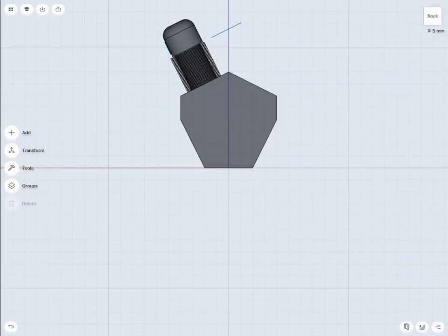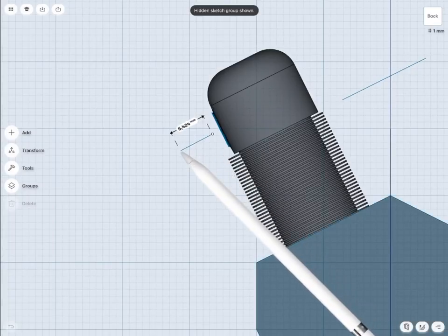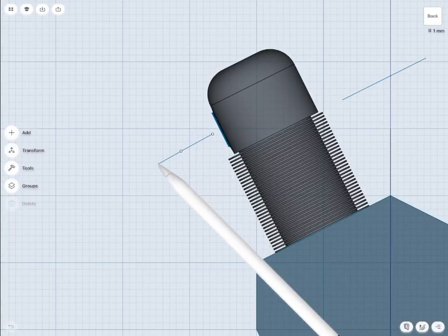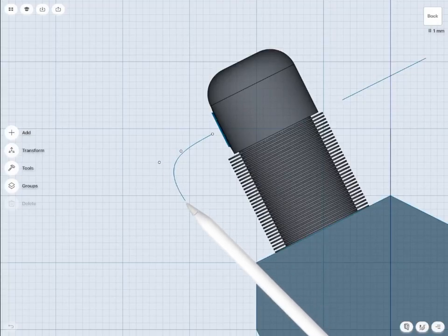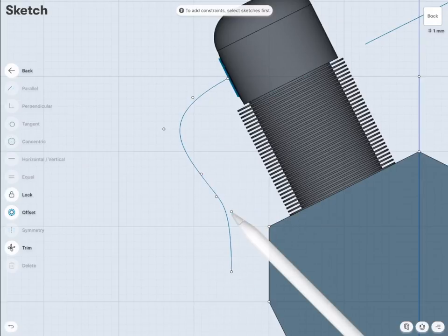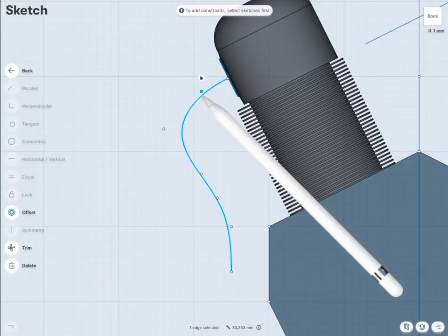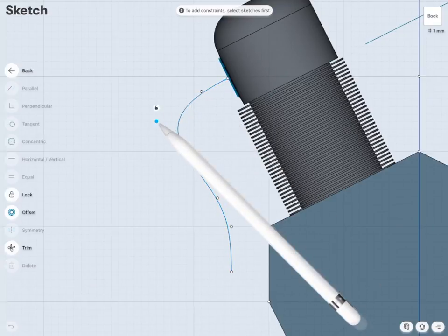Now, I'm going to create pipes using the circles I've used to create the holes in the valve cover. So now, I will create a spline to use with the sweep tool. Try to keep it as perpendicular as you can at the beginning of its creation. This will help the sweeping process to be more efficient in the future. Afterwards, we can adjust the position of the points at any stage you prefer.